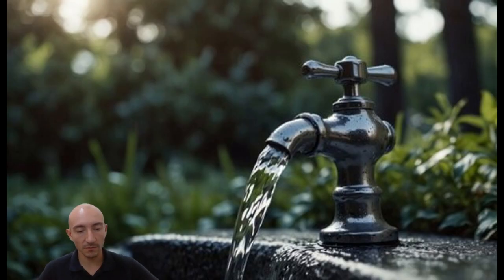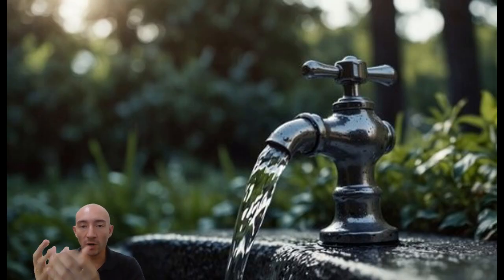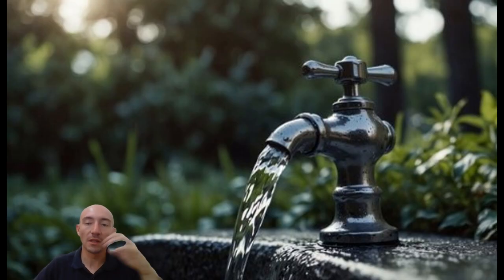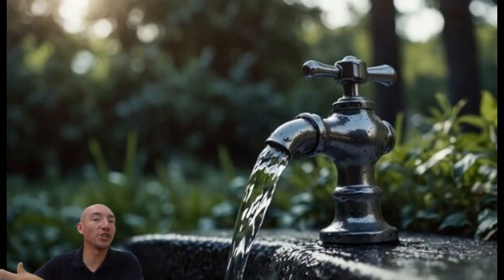Imagine the opposite. If you don't have nozzles and you have just a stream of water, part of the mash is going to receive a lot of water, and part of the mash is going to be dry. And even though you have paddles that will try to mix everything, you won't be able to. The paddles won't be able to compensate for this poor water injection.